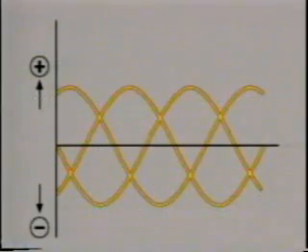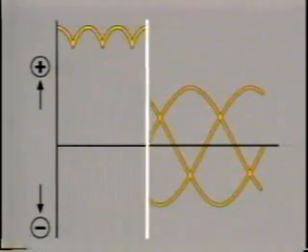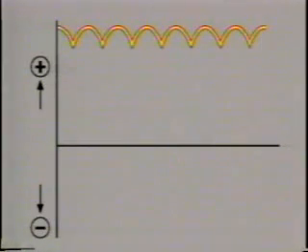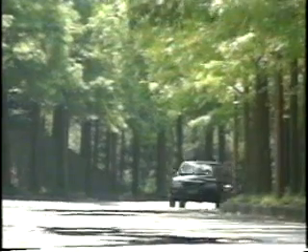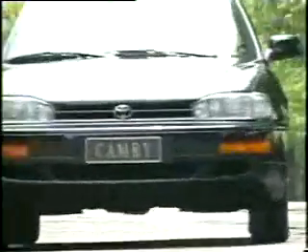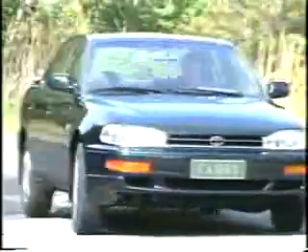The alternator produces three-phase alternating current, so the direct current after rectification is as shown. This is what a rectifier looks like. One more problem remains, however. The rotation of the engine varies according to the vehicle speed, and the faster the rotation of the engine, the more current is generated.